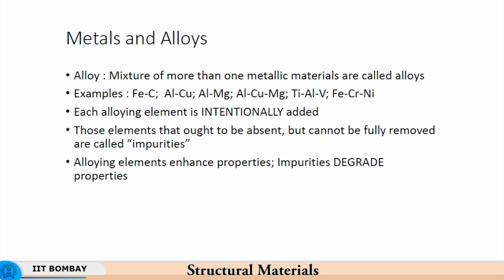So, you need to alloy them to enhance their properties, because when you have service conditions, they are not just about strength at a particular temperature. You have a big variety of service conditions which need to be satisfied simultaneously, due to which a single material might not be able to stand up to all those conditions, and that is the reason why we alloy carbon with iron, for example.